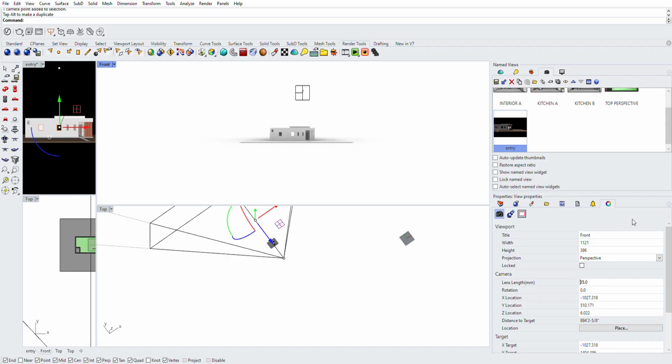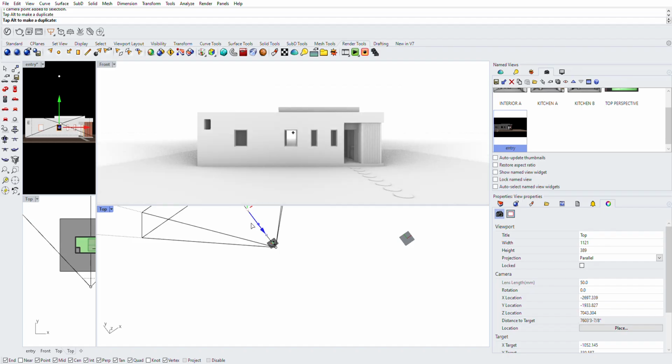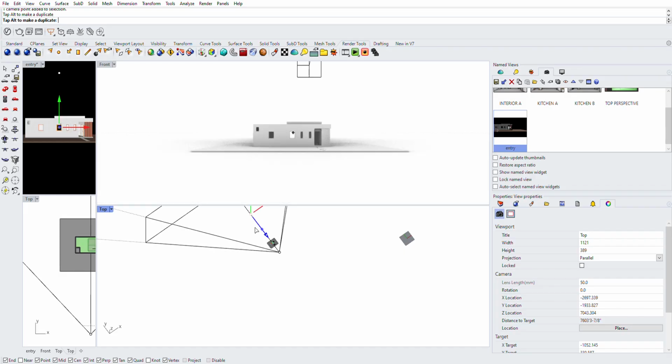But the lower this number, the more distortion is happening, but you're getting a lot more in the frame. And so generally for interiors, we do lower numbers, like in the 14 to 24 range, dependent on the size of the space. That can be larger if needed, but for exteriors, it's more common to be doing a higher value. But generally, it depends on what you want the feel of your view to be. If you want your building to appear small, it's probably better to have a higher focal length and shoot it from farther back.